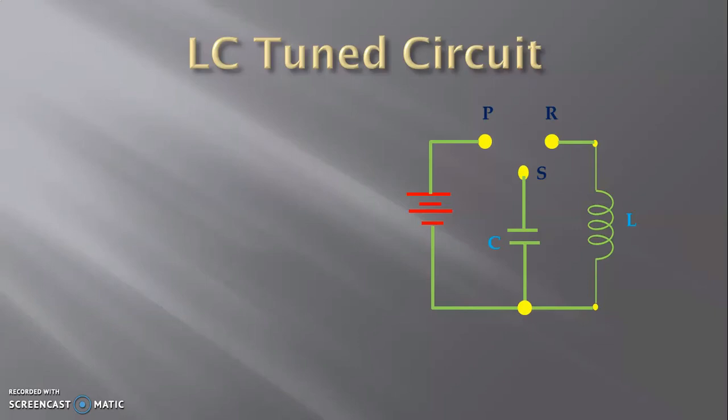Either it can be connected to P or it can be connected to R. When it is connected to P, the capacitor is connected across the power supply, and when it is connected to R, it is connected across the inductor L. So parallel L and C is known as an LC tank circuit or LC tuned circuit, which is responsible for generating the oscillations.